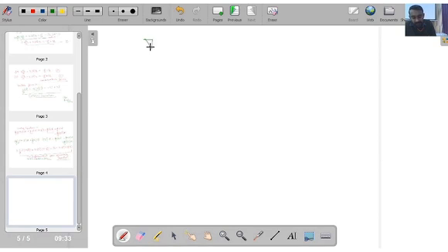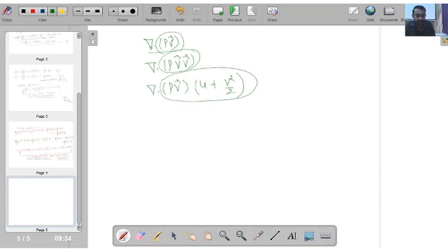Okay, so the terms which are having divergence of rho v vector, and divergence of rho v vector into u plus v square by 2. When the complete term is inside the del operator, this is in the continuity equation, this is in the momentum equation, and this is in the energy equation.